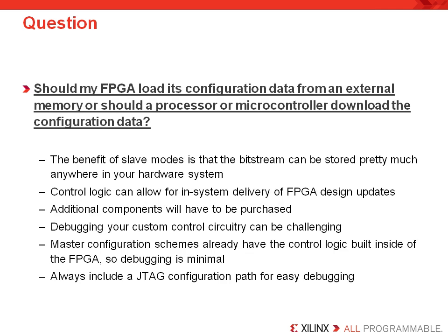My first question: should my FPGA load its configuration data from an external memory resource, or should a processor or microcontroller download the configuration data? Well, the benefit of slave configuration modes is that the bitstream can be stored pretty much anywhere in your hardware system. You can store your bitstream on a flash, laptop, hard disk, or somewhere on your network. Your system can basically be whatever you're willing to build.